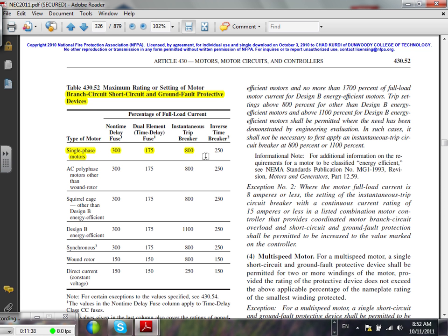And Phil, my friend, he loves these circuit breakers that are sitting right here. These are called molded case circuit breakers, the last one, right? And he wants to use them with a motor. In a case like this, what would my multiplier be? Inverse time circuit breaker, 250. What do you do? You take the full load current, guys, and multiply it by these multipliers. Any questions?